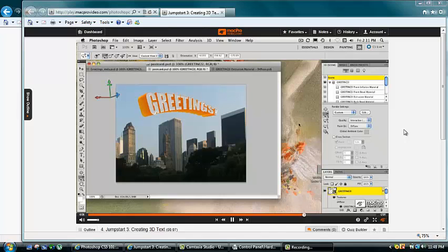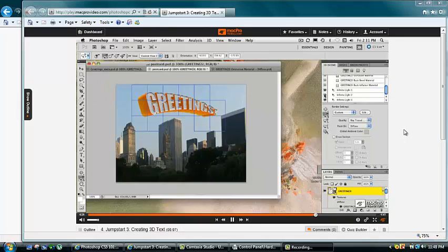And if I'm happy with that, I can go ahead and take a look at it with my interactive to ray traced instead. When you switch to ray tracing on the quality of your scene, again, you can see now what's happening with shadows. Now the shadows are controlled by the extrusions and the bevels, but it's also controlled by lights. And if we go down in the scene, you can see that we have three what are known as infinite lights. These lights can't really be pointed, but they can be positioned a little bit in space. And each one makes it look a little bit different.